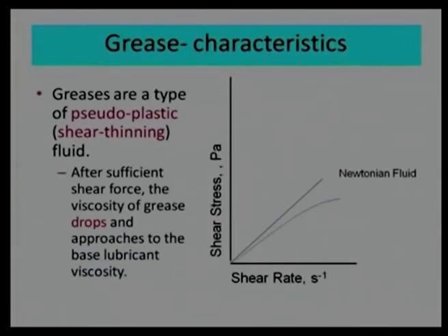To model this kind of grease, we use some sort of fluid law, maybe Newtonian law, shear thinning law, shear thickening law, or Bingham law. But we know very well that grease acts as a pseudoplastic. They show shear thinning behavior, but they also show some resistance initially.